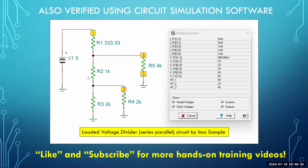So let's see what the simulator shows up. We're looking at IR2. So IR2, lo and behold, 2 milliamps, just like we predicted with our calculations, just like we measured a moment ago using the breadboard.